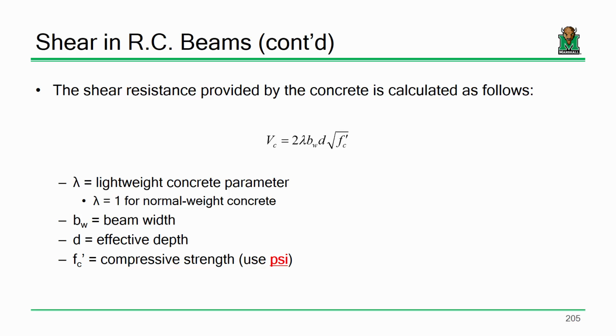No. We've talked about this before. That's square root of f'c. Remember, when you're dealing with square root of f'c, that's that empirical model. You put in psi, you get out psi. Calculate that. You put in 4 as opposed to 4,000, you will get a different number. And I promise you it will be the wrong answer. It's an empirical model. We've discussed this before. So, sound good?